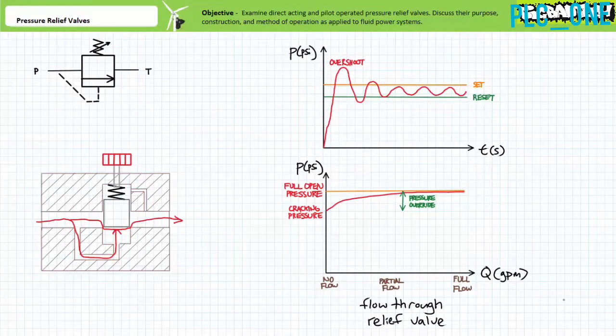Cracking pressure is something that must be anticipated in a system and accounted for. If a system did truly need to operate at full flow capacity up to 800 psi, the pressure relief valve would have to be adjusted up to 900 psi to account for this valve's early cracking pressure and 100 psi pressure override region. This newer, higher pressure limit may, however, necessitate more robust components, fittings, and conductors.